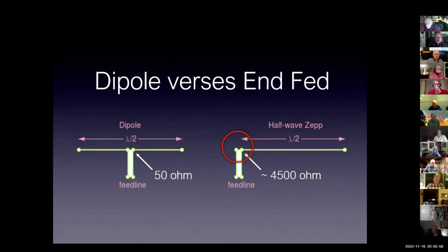The feed point typically is 72 ohms, somewhere near 50 ohms to match to coax, which is good. Makes it pretty simple. If you've got some coax, you can cut a couple pieces of wire, quarter wave length long, and put up an insulator and feed it and hang it up in the trees.